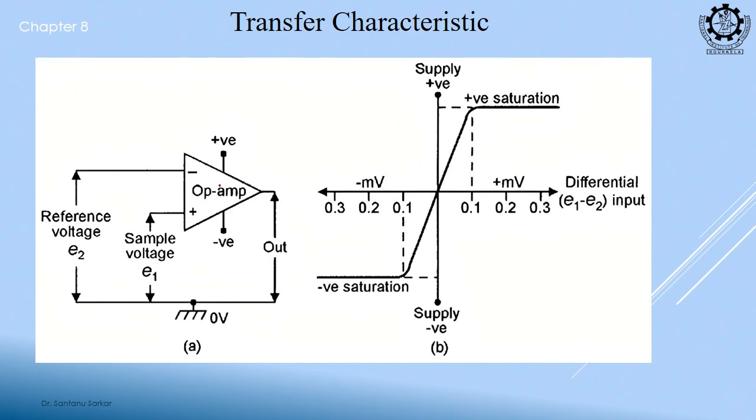So, this op amp, which is basically a basic topology, is a diff amp. We know that we have 2 inputs and actually we are having 2 outputs. If we subtract them, we get a single output. So, this output is actually, you can think of as VO2 minus VO1.